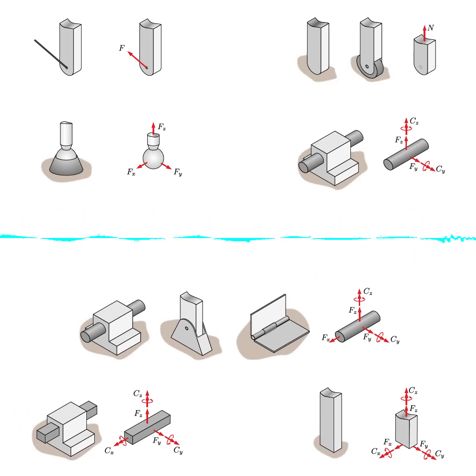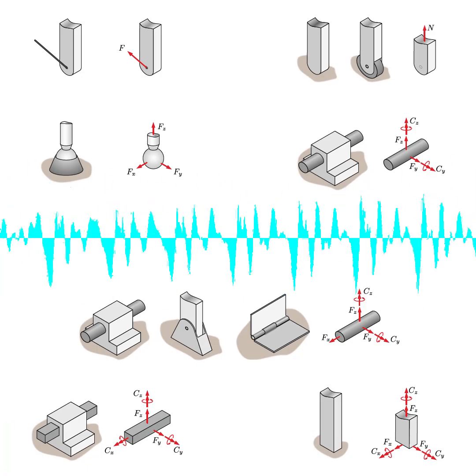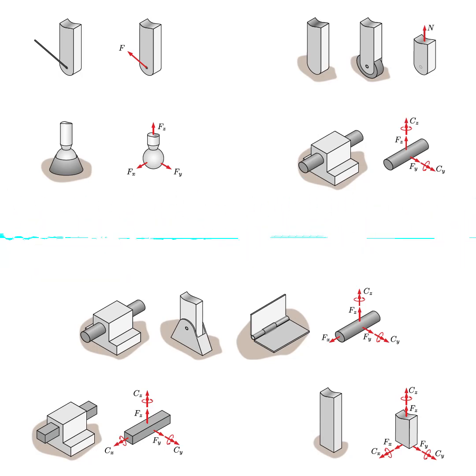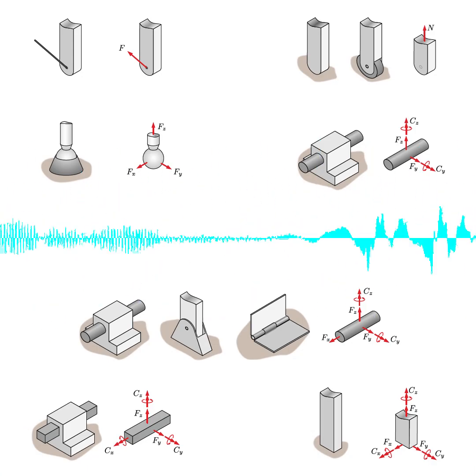And when we're summing moments in 3D, it's not just the moments caused by forces anymore. The source mentions something called applied couple moments. Right, so in 3D, you have to consider both those moments that are generated by forces, which you calculate using the cross product, and any externally applied couple moments that might be acting on the body. What are those couple moments again? They basically cause rotation without any net force.